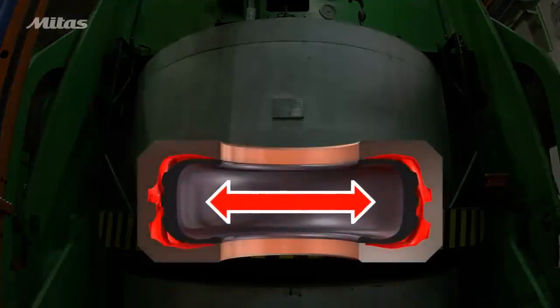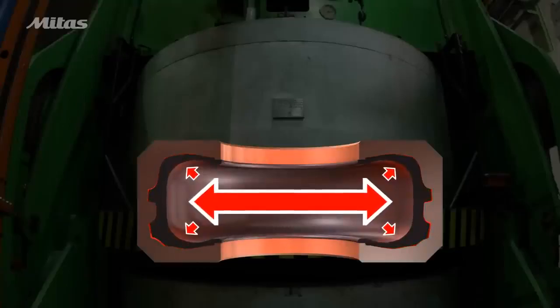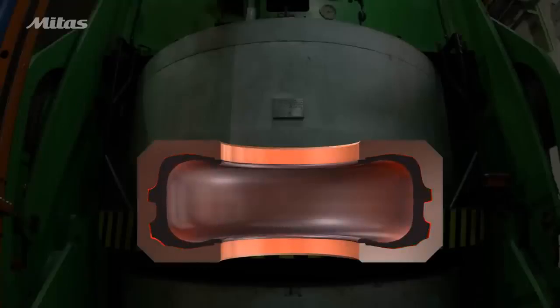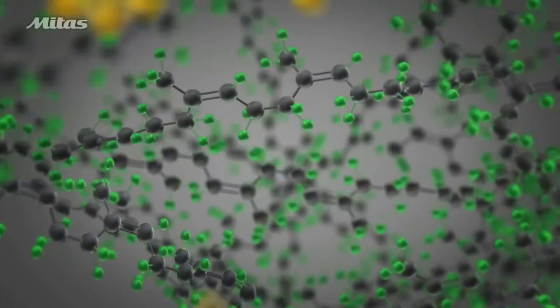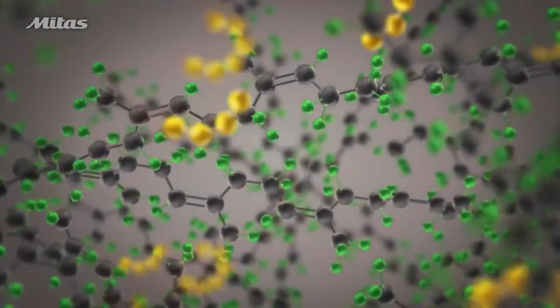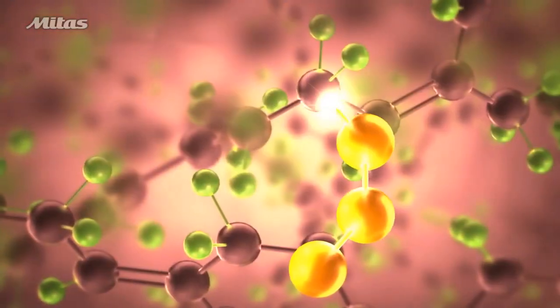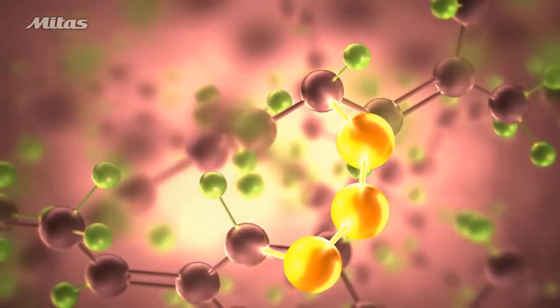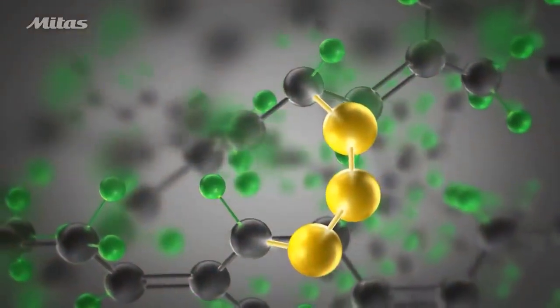The rubber compound is heated and becomes plastic. It fills the mold. The vent system lets the excess air escape the mold so that the rubber fills the mold completely. The applied heat also initiates a process called vulcanization. This is the basic element of natural rubber molecule, a polymer. During vulcanization, these polymers are linked by sulfur. This changes the molecular structure into a three-dimensional pattern of interlinked polymers.